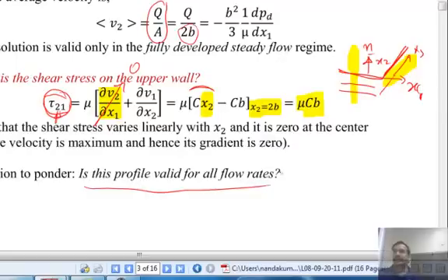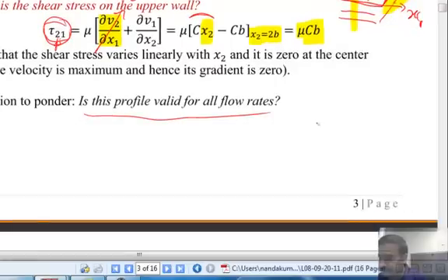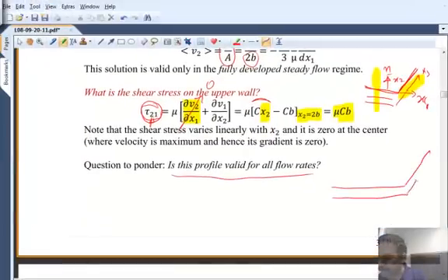If I ask you to design an experiment, would that be possible? You need two infinitely long parallel plates. That's where the challenge would be. And then you need a way of pumping the fluid through those two parallel plates. But one can come close to the approximation if I design, for example, a finite but very long channel.